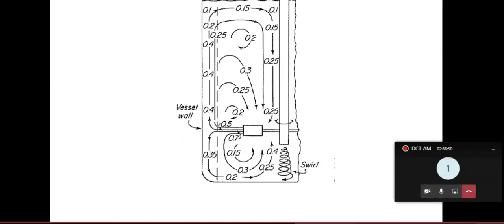First, every time I used to say, whenever you are going to start a reactor, check the bottom valve of the reactor. If the bottom valve is not closed, if you pump, the material will go to the second process. So what will happen? Without processing, the raw materials of the first reactor go to the second reactor. Everything is going down. Your batch is destroyed. So hence, there is a procedural approach to run a factory, which we are all supposed to follow.